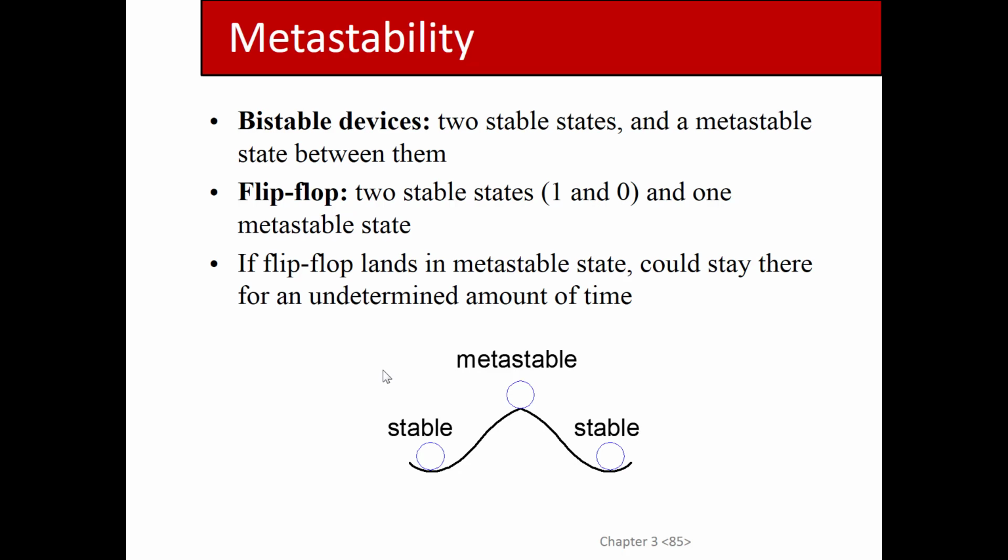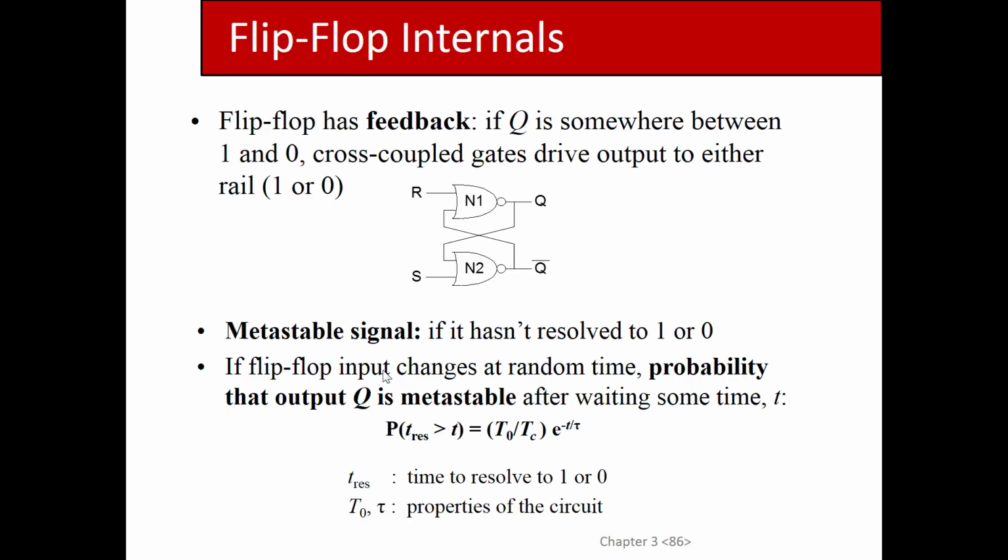So there are two main factors: when it happened inside the aperture, and the internal characteristics of the circuit. But suffice it to say, it's not going to happen inside the propagation delay that you get from Artisan or whatever company supplied your cell library. So we have this weird sort of uncertainty.